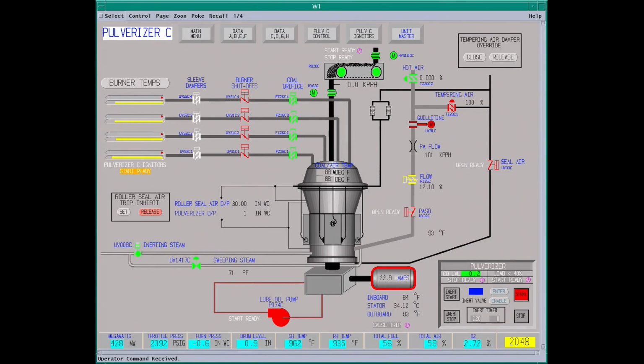Outlet temperature, this is huge. You can tell if you have a fire in the pulverizer. You do have fires in them occasionally. You want this at about 140 when we're running. It's running, we're just giving it a second to blow any coal out of this thing. Sometimes you can grind these to the boiler if you trip off, lose one. You can start up and keep the airflow real low and slowly feed in the coal dust. But if we trip off, they have to grind them out. You put inerting steam on, then you grind it, and all the coal in here dumps out the pyrite hopper. So you basically get all the coal out of these.